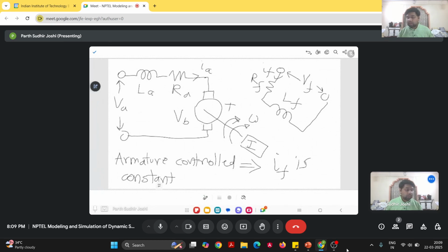And similarly the back EMF VB will be proportional to the armature rotation and the flux linked to the coil, which is again proportional to the magnetic field. So it is proportional to the speed of rotation of the armature and the rate of change of flux. The flux is proportional to the magnetic field. So we can write VB is minus K2 into B omega.